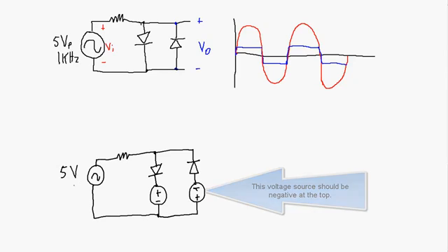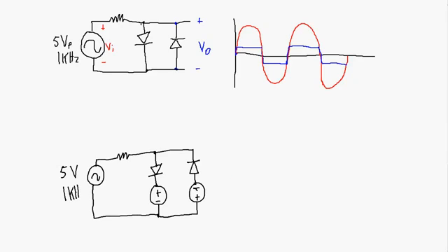So we're going to have our 5-volt input signal again at 1 kilohertz, although the frequency in this case doesn't really matter so much, because I don't care about the time scale. What is important though here is what are these two offsets? Well, this first one is going to be at 1.3 volts. The second one is going to be at 2.3 volts, but you see it's in the opposite orientation, so relative to this one it's negative 2.3 volts. And then I'll have my output over here. I'll do my output in blue, V out, and my input is red.